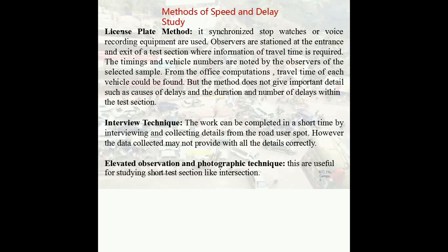Another method of speed and delay study is the license plate method. If synchronized stopwatches or voice recording equipment are used, observers are stationed at the entrance and exit of the test section where information of travel time is required.